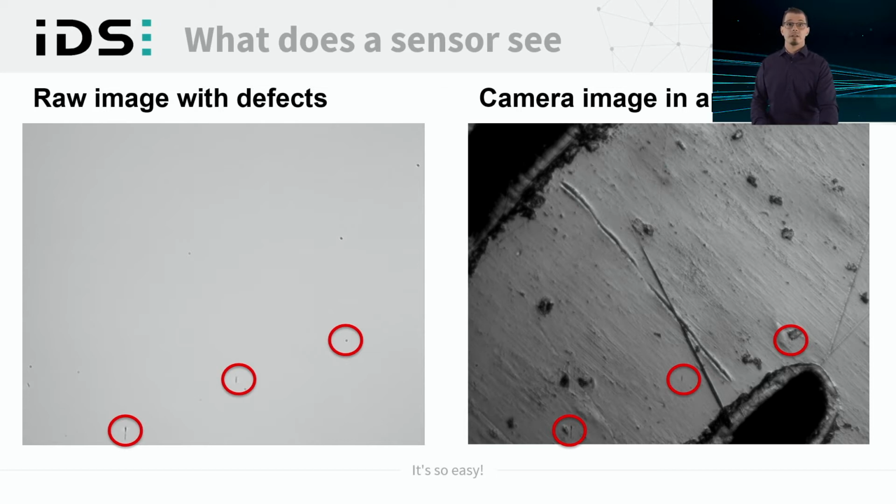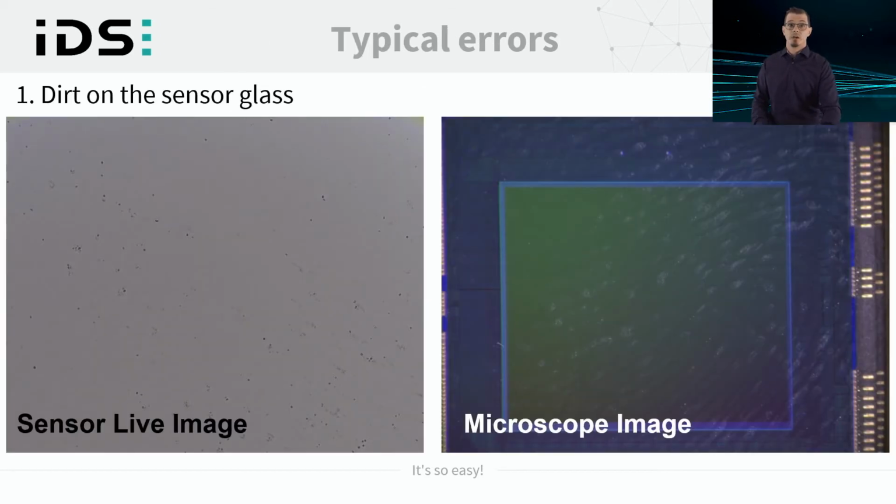Assuming that a defect is visible, in the following let's take a look at some typical defects or dirt and how they differ. Dirt on the sensor cover glass. Very often there is dirt or residues from the manufacturing process on the sensor itself. Mostly loose dirt, which will be cleaned in our standard production process. This dirt can often be removed with cleaned and dried compressed air or isopropyl alcohol. The loose dirt is visible in the camera image as a dark or black spot.